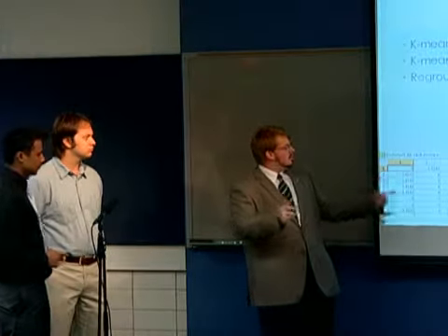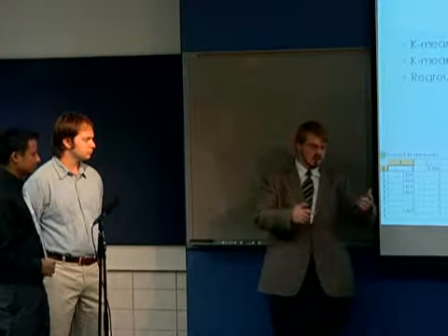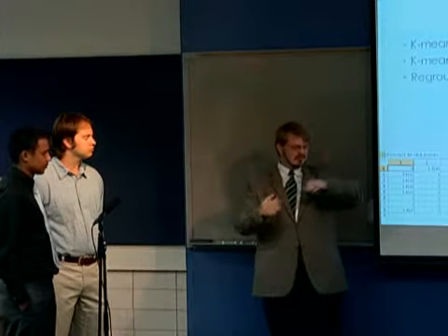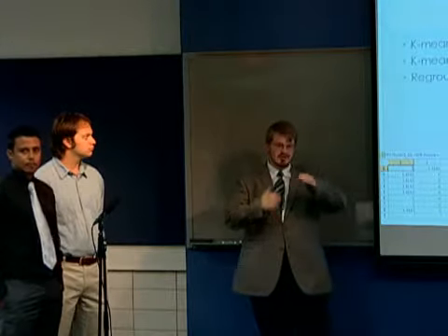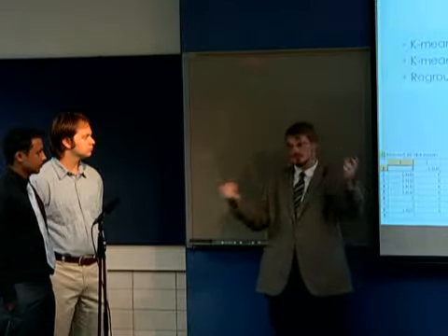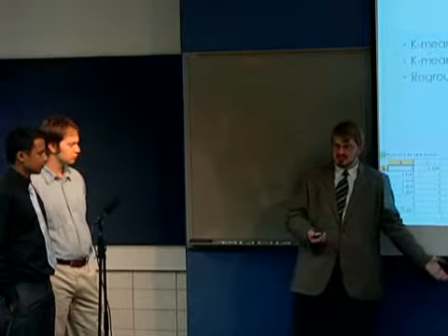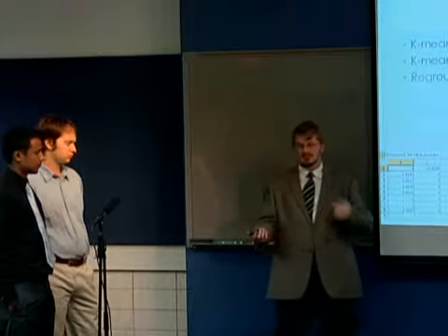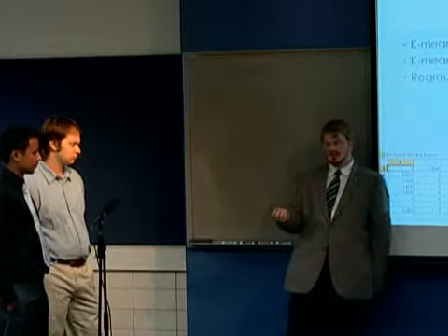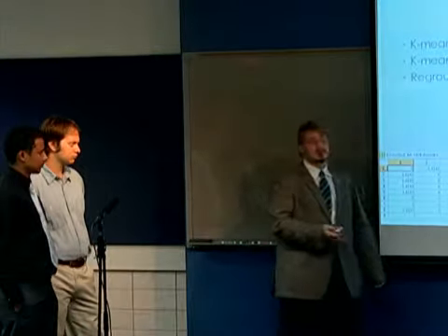But after this, the real trick is to take that long list of 64 points or whatever and somehow gray code it. So I used something really simple. I just k-meansed it and sorted based off of it, and I iterated that a few times just to sort it so the points that should be in the same clustering should be all together effectively. So that made the most sense. And then I put a running gray code list next to it and sorted that way. So you could just index the partition easily and assume that's the gray code value. So it's a simple, stupid way of doing it, but it works, hopefully.